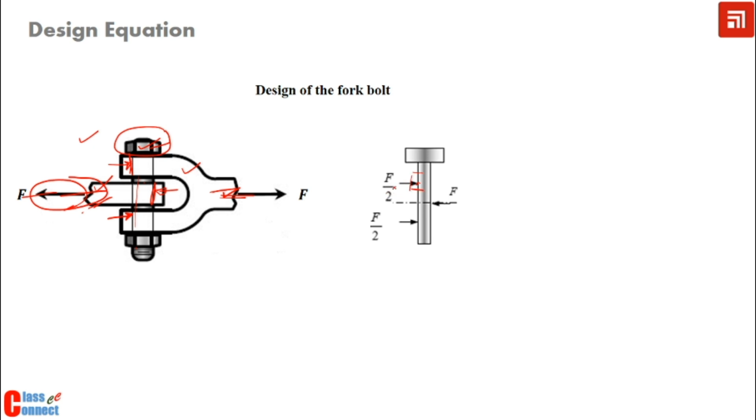And this is no doubt our assumption, and this assumption may vary from case to case, may vary from designer to designer, but with a proper justification that we'll be discussing in detail when we discuss the design of pin. But right now we can say either we can assume whatever load is acting on the interface is acting at the midpoint of this, or we can also assume that the load is acting in a triangular fashion. There is no load here and maximum load here, and the load in that case will,